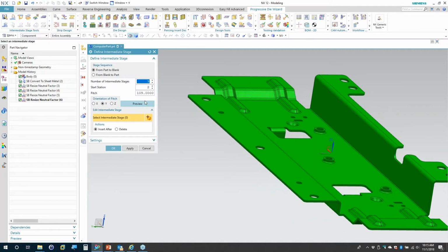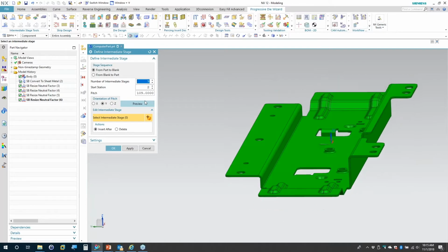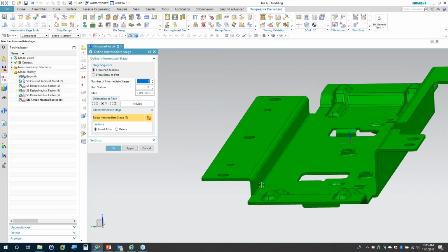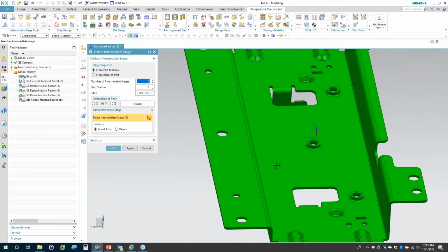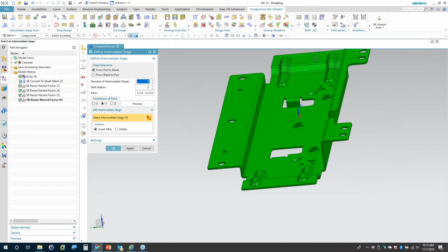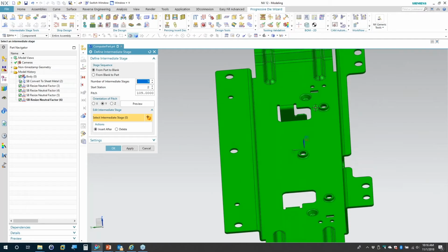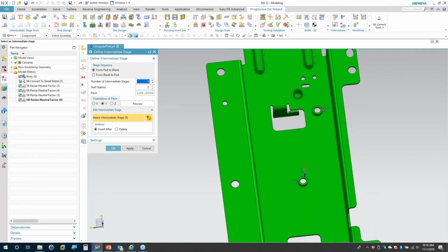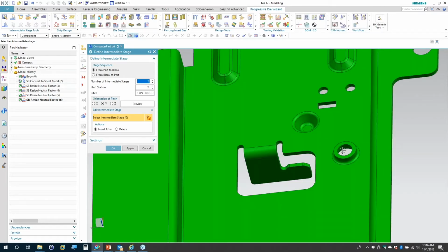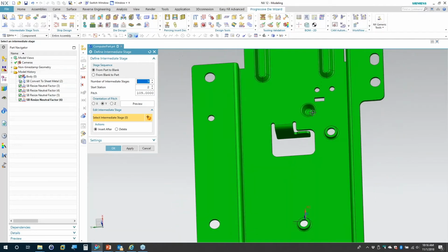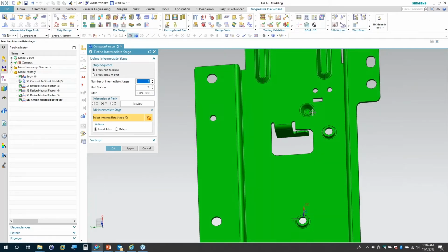So we've got this part, and we're going to try to envision how this thing is going to be manufactured. So we've got a number of flanges here that are bent twice. So we might have two different stages for those. They're on four sides of the part, so let's kind of double that, maybe 4 stages. We've got some punch features, some internal flanges. So let's see, we've got up to 5, 6. Some internal, you see some cutouts, raised shapes here, 7, 8. So let's go with 8 stages.